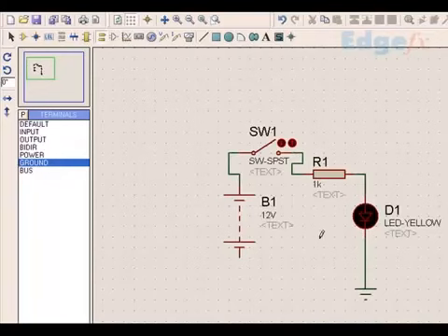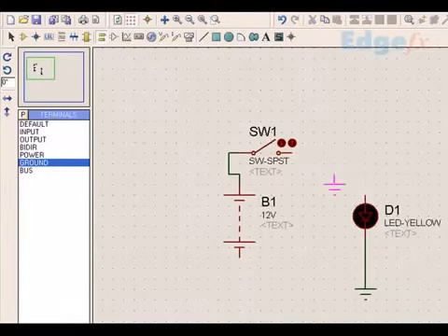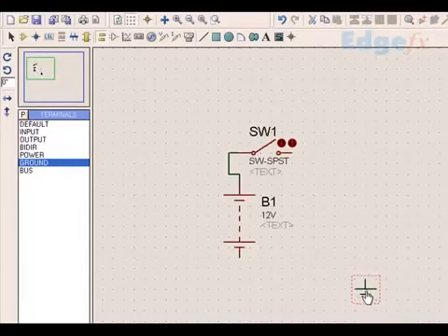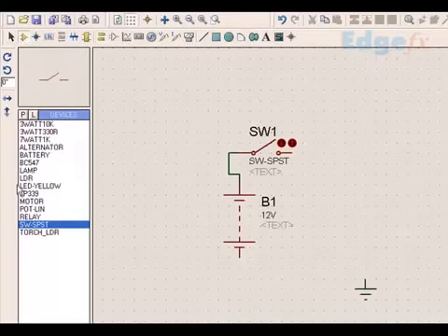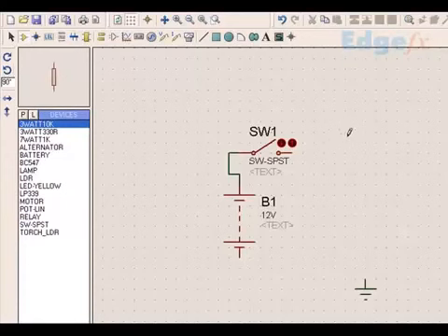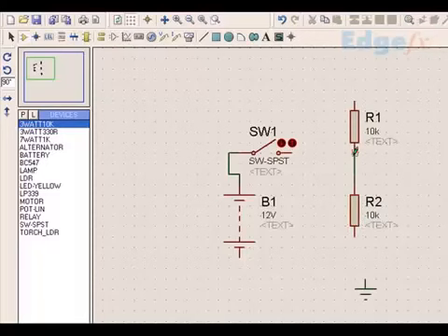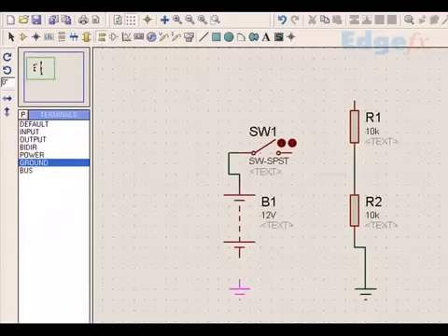Next we go over to a very simple operation that we all know, the voltage divider. What is a voltage divider? For example, we take a 10K resistor and I put a 10K resistor here, another 10K resistor here, and connect it this way. And as usual, I must have a ground connection for the path to be complete.